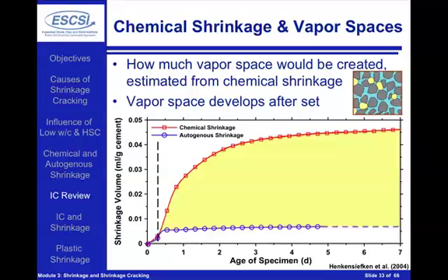So how do we determine how much water we're going to have in the system? We essentially are looking at placing enough internal curing water to fill in the volume that's created by chemical shrinkage. As we mentioned earlier, we can measure the chemical shrinkage either using the ASTM test, where you essentially have a small vial with a pipette on the top and you can measure the volume change, or we could use the buoyant technique, where we're essentially measuring a mass over time and converting that over.